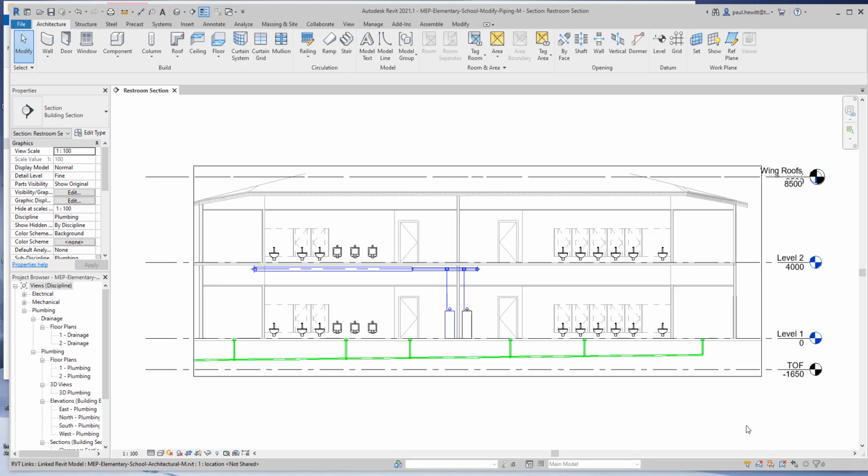In our previous video, we added both hot and cold piping and a sanitary piping where we use standard as a placeholder. In this video, we'll change the type of piping run to the correct sanitary type. We'll modify the size and location of pipes, and we'll connect two classroom sinks to the hot and cold water mains, and then copy the sinks and piping along the hallway.